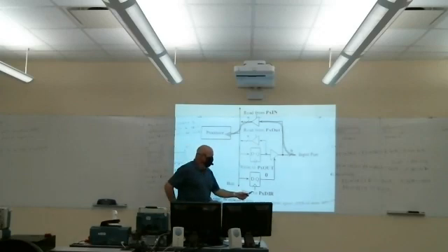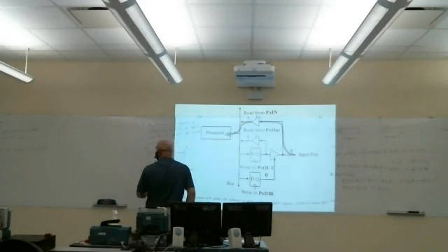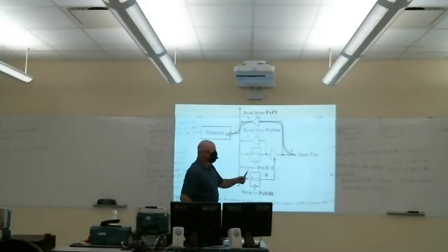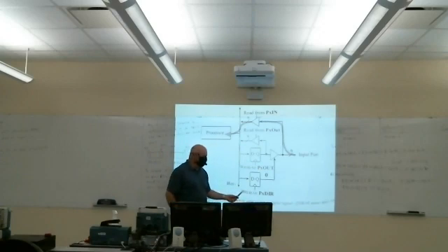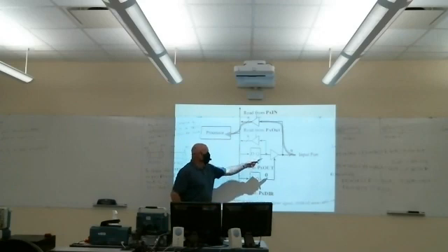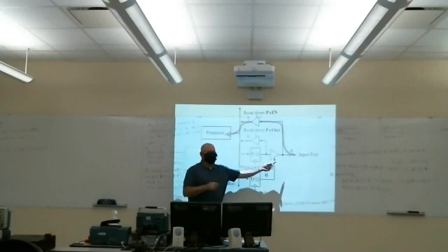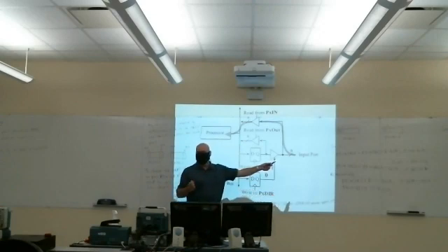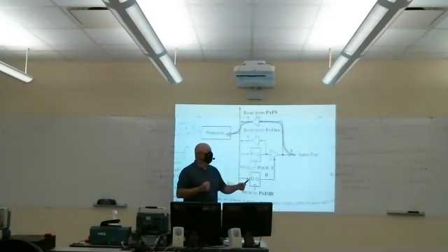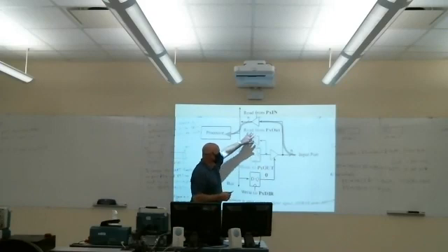So we have to write, what was the example, I guess? Well, there we set them up differently. But we have to write to the direction register. And we have to write a 0 if we want to use that corresponding pin as an input pin. And that means input to the microcontroller. So this is where we would hook up like a switch, for example. Okay. And you can ignore all of this because it's used for the output function.